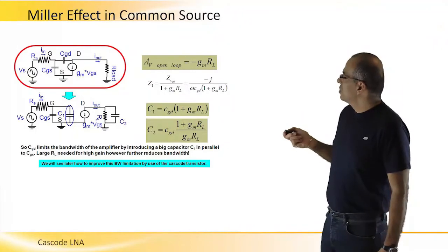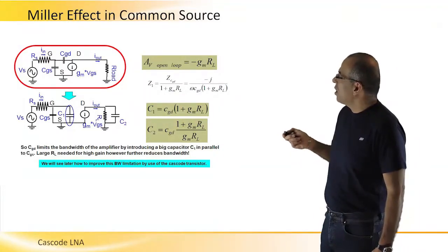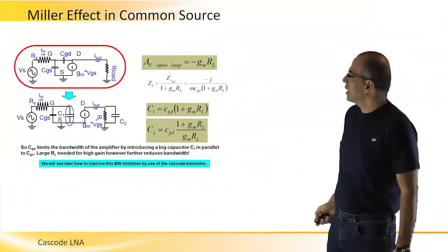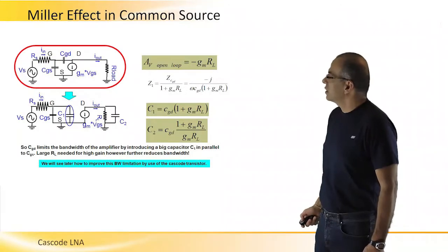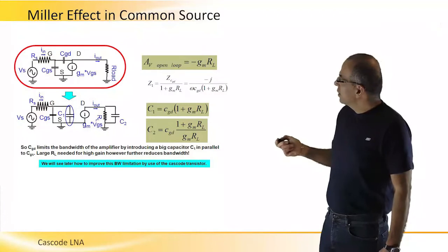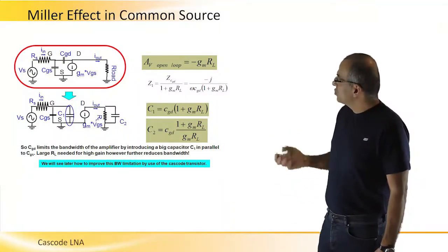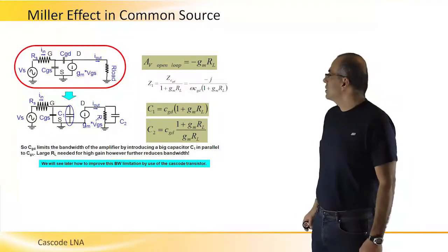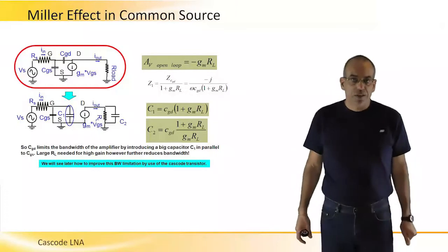And as we know, this amplifier will have a gain of GM R, our load, if we want to look at the output as the voltage gain. And so we want to replace CGD now with two input-output impedances in order to analyze the effect on bandwidth that it has.